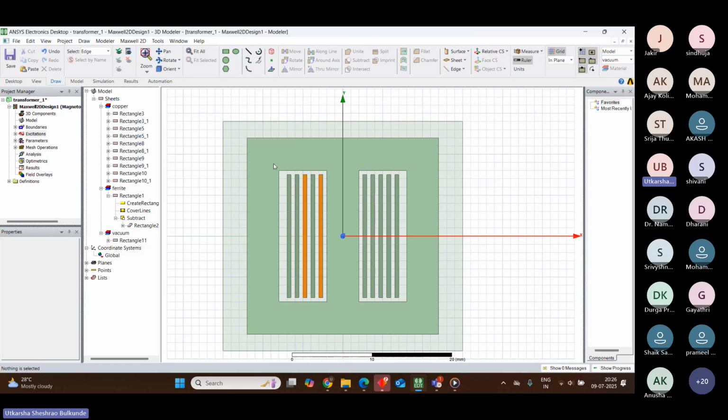Because this was a bigger cross section. These are smaller cross sections. That's why we are keeping a small mesh for this and somewhat bigger mesh for this, for accuracy. Understood? Okay, ma'am. Yes, ma'am. Okay.